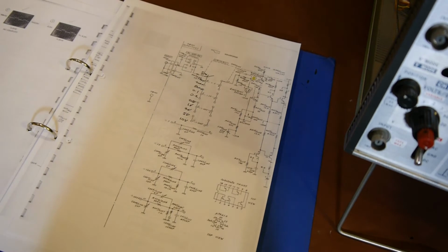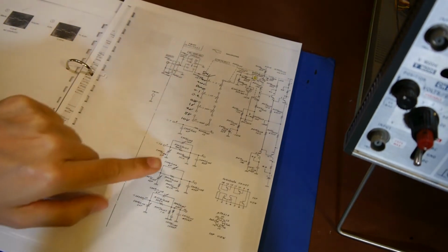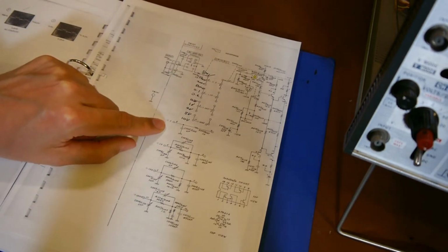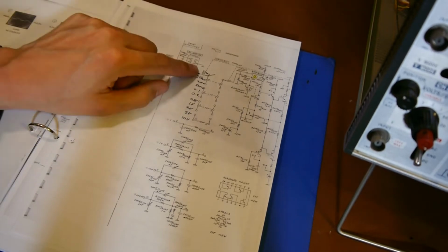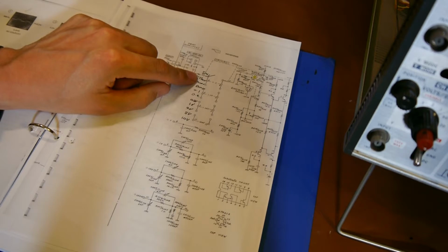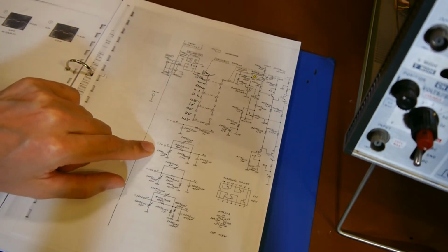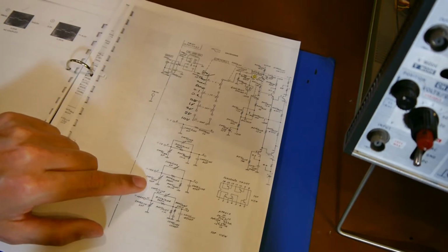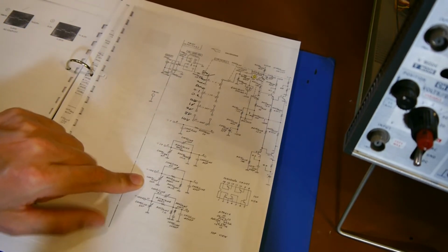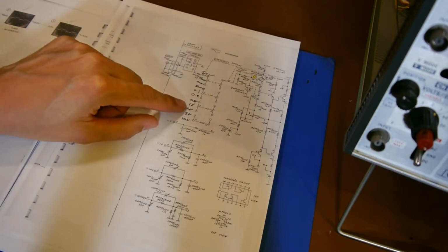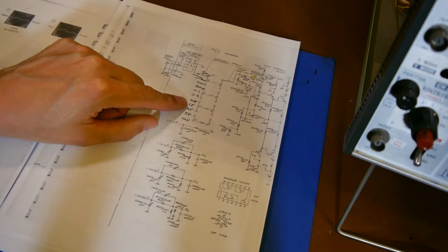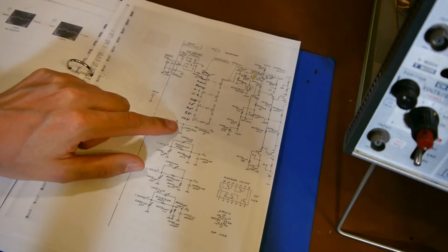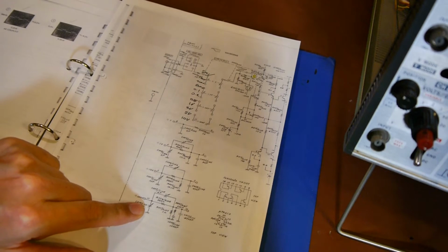Okay, let's have a look at the actual attenuator circuits now. It's actually split out in the manual here. So there's the divide by 1, which is used for the 5 millivolts and 10 millivolts per division range. Then we've got the divide by 10, which is used for the 50 millivolts, 0.1 and 0.2 volts. And now we've got our suspect one, the divide by 100, which is used on our 0.5, 1 and 2 volt ranges. That's the one that's giving us jip at the moment, that doesn't appear to be working properly. And then finally we've got our divide by 1000 range, which is for the 5 and the 10 volts.